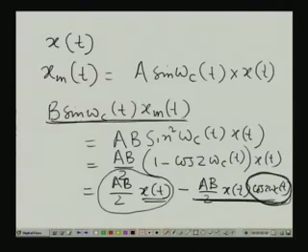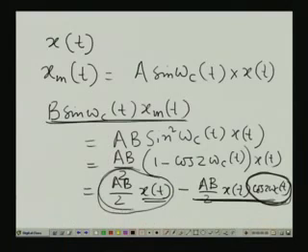So now this signal is actually a sum of a 0 to 5 or 10 hertz signal and a signal which is around 10 kilohertz, very narrow. So it is very simple to separate these two. Any simple low pass filter, since there is so much separation, will cut off this 10 kilohertz signal and give you the 5 hertz signal, which is this x(t). This is the basic principle of phase sensitive demodulation.